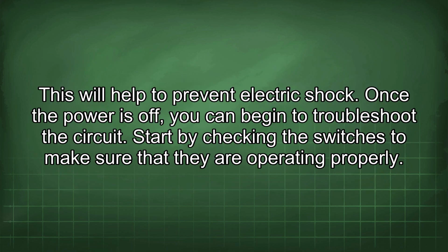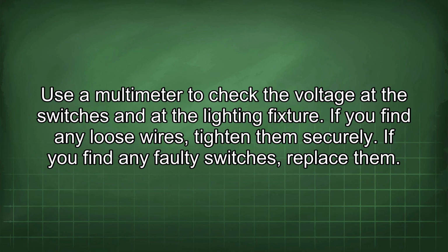This will help to prevent electric shock. Once the power is off, you can begin to troubleshoot the circuit. Start by checking the switches to make sure that they are operating properly. Use a multimeter to check the voltage at the switches and at the lighting fixture.